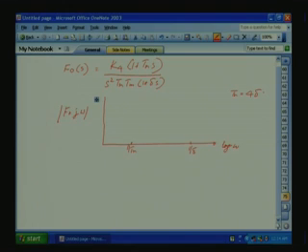Till this corner frequency is approached, S square is the dominating factor, so it will come with minus 40 dB per decade. Then the zero will come, it will give a lead, and finally it will give minus 20 dB per decade. So, we choose Tn sufficiently away from delta.